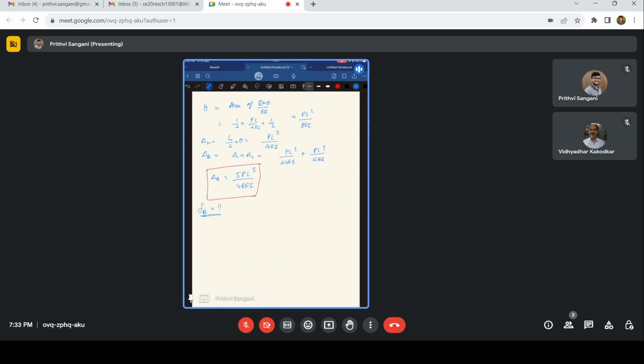At the same time, MA has to be 120, but right now it is taking more bending moment, that is 132.46. And the shear force before was around 60 kilonewtons, but now it is about 62.1 kilonewtons. So again, support settlements have to be taken into account when we are designing the structure. Support settlements induce bending moments, right? It increases the bending moment. So that is what we have learned from this example.